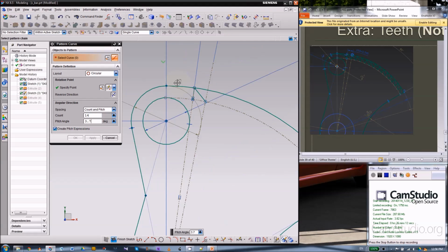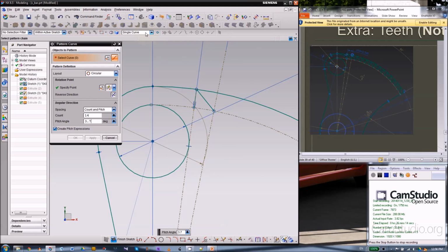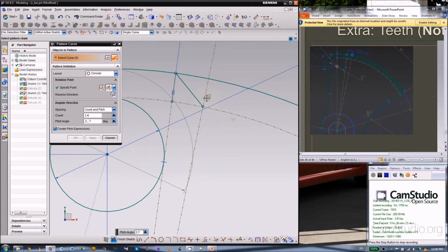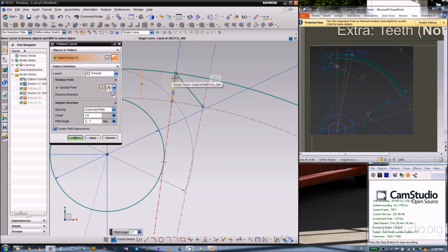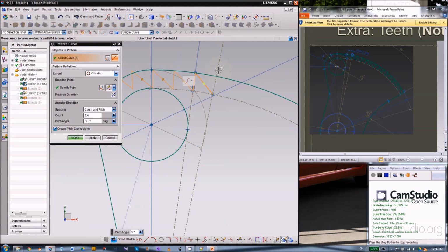And here we also have curve rule. Okay, by default it will be a connected curve. You want to pick single curve only because you don't want to pick a whole bunch of different curves. So make sure you're picking up the short solid line instead of the dashed line. The second one, and we have the wrong direction.